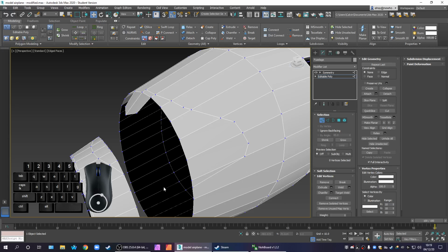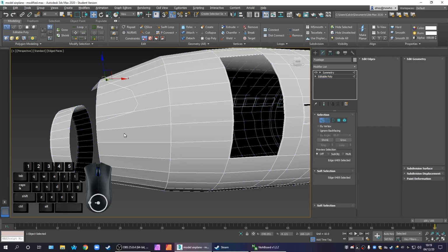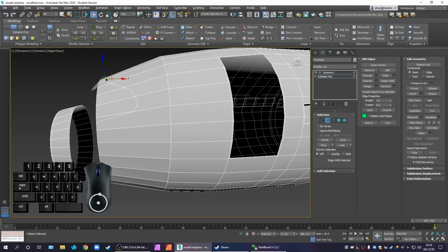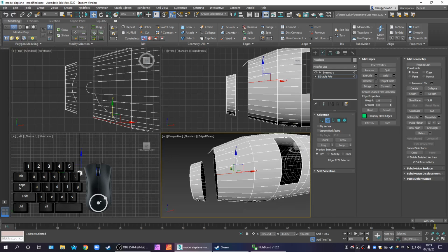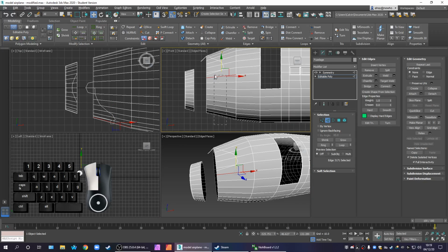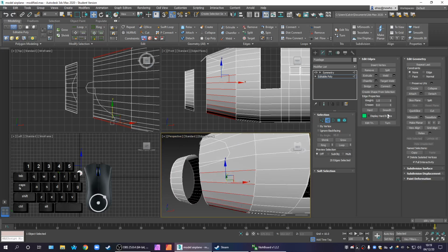We still got to figure out how to cut the rest of this in. So what I was going to do, before I got so rudely interrupted by my own poor plan, is put an edge down here. And I'm going to do it by selecting these. Ignore back facing is off. I'm going to choose.